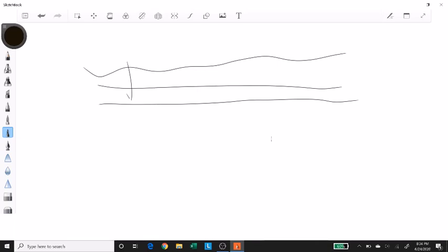So if this is my land and your supply pipes are usually below the ground, and I have decided on a slope, so now I need to excavate. And how much to excavate? I can use my level by first finding out these excavation heights on paper, and then I can use my instrument to go in the field and actually find out those depths. So it helps not only in control survey, but it also helps in execution as well. So this was all about finding out relative height difference between two points.